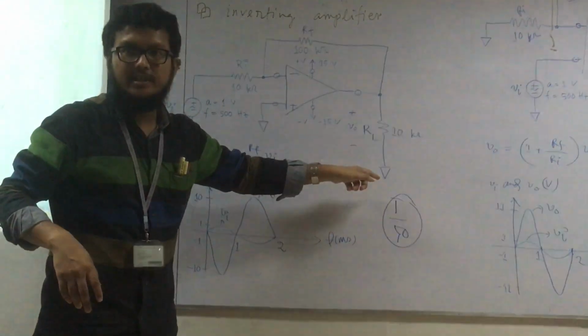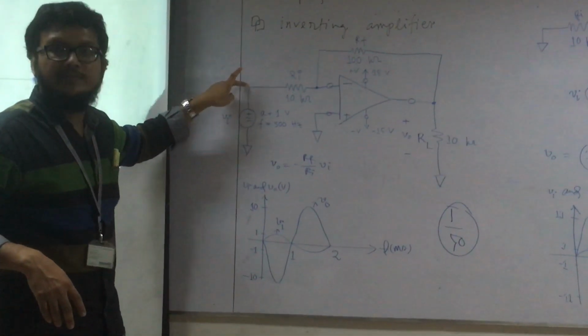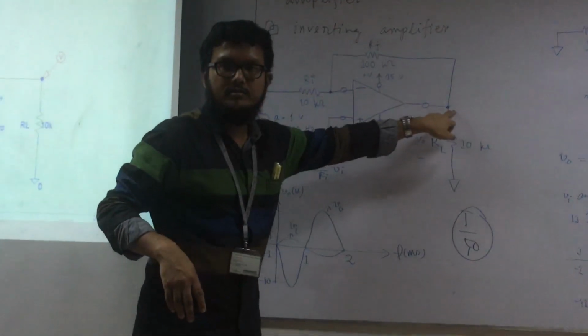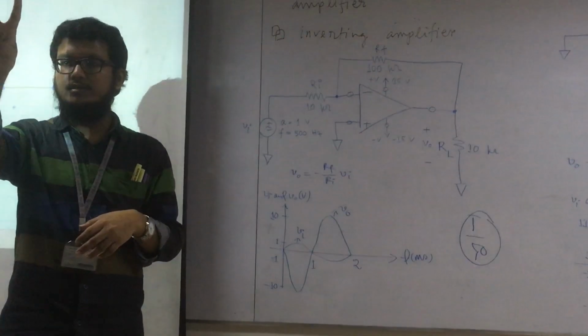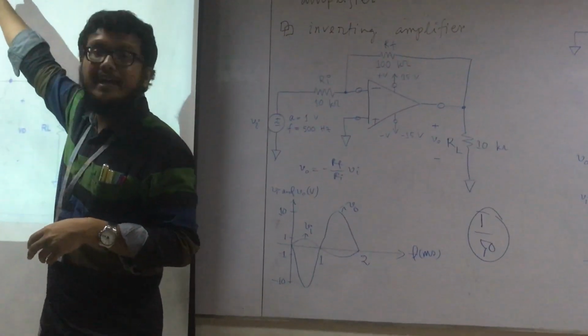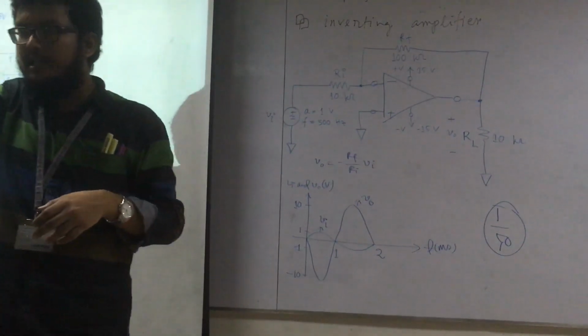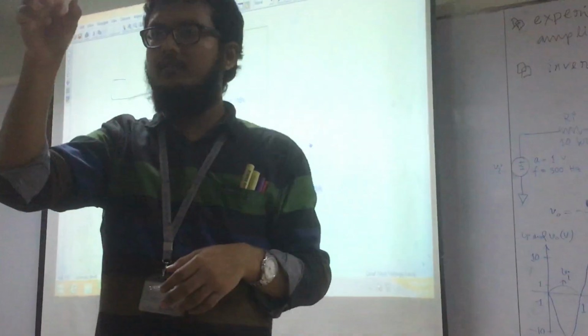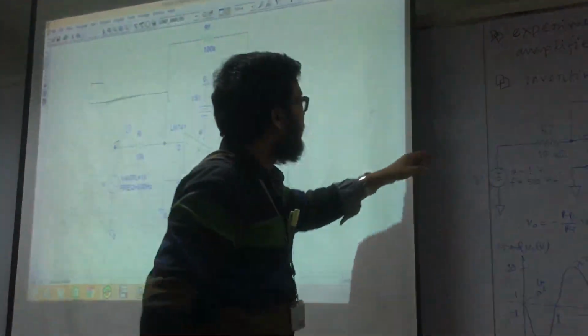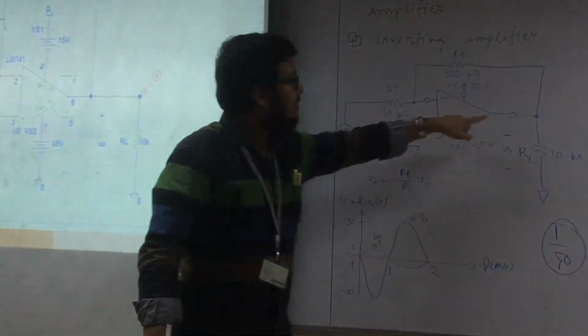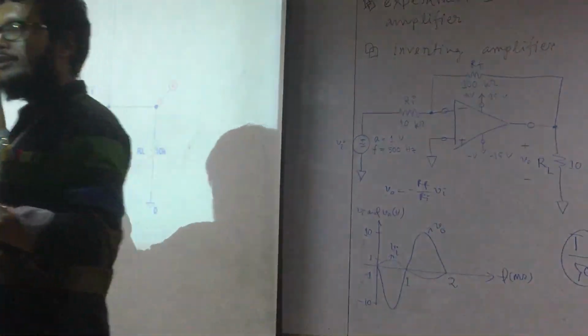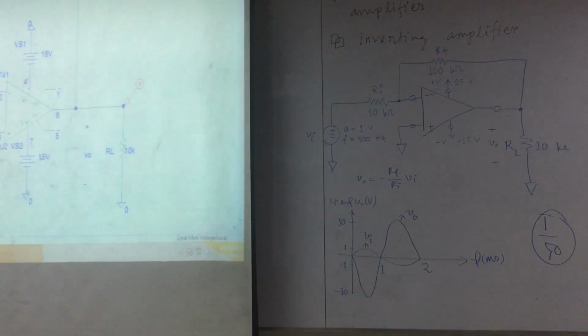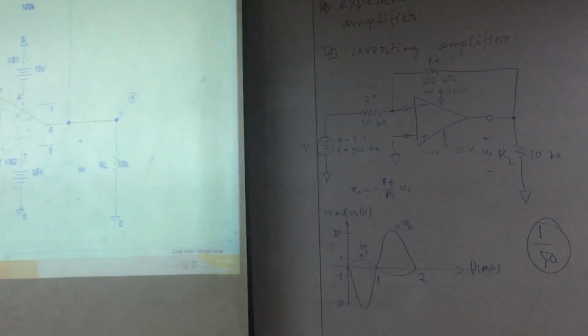These two, according to their outlook, are nothing but the nodal voltage of this node and that node. That's why we're going to use two nodal markers. Okay? You can get it from the marker menu, and the first option, mark voltage / level, is the nodal marker. You take it and place one copy here, another copy there. That's how you do it. Okay, so done with saving.